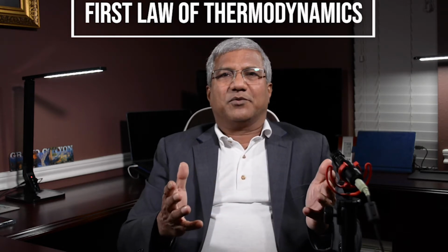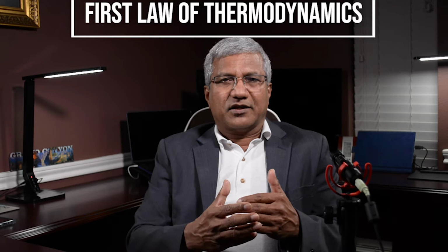In this part, we will learn about the first law of thermodynamics, which is the relation between heat, work, and internal energy. We will look at the differences between isothermal changes and adiabatic changes, derive equations for them, and also obtain equations for work done during an isothermal change and an adiabatic change. We will end this section with a number of problems worked out using the concepts. So let's get into it.